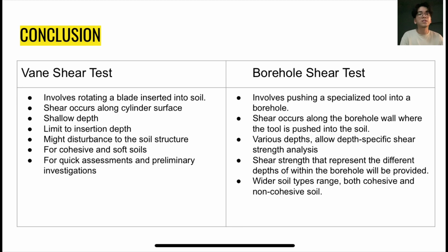For the borehole test, we can conclude that it involves pushing a specialized tool into a borehole, and shear occurs along the borehole wall where the tool is pushed into the soil. It has various depths, allowing depth-specific shear strength analysis, and shear strength representing the different depths within the borehole will be provided. It covers a wider range of soil types, both cohesive and non-cohesive soil. I think that's all from me.